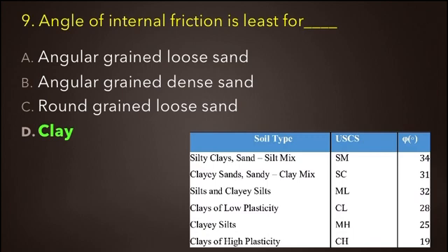These pure clays are very rarely found on top of the soil. The angle of internal friction value increases with increase in the quantity of sand in the clay. For your information, the angle of internal friction for clay is usually in the range of 5 to 20 degrees.